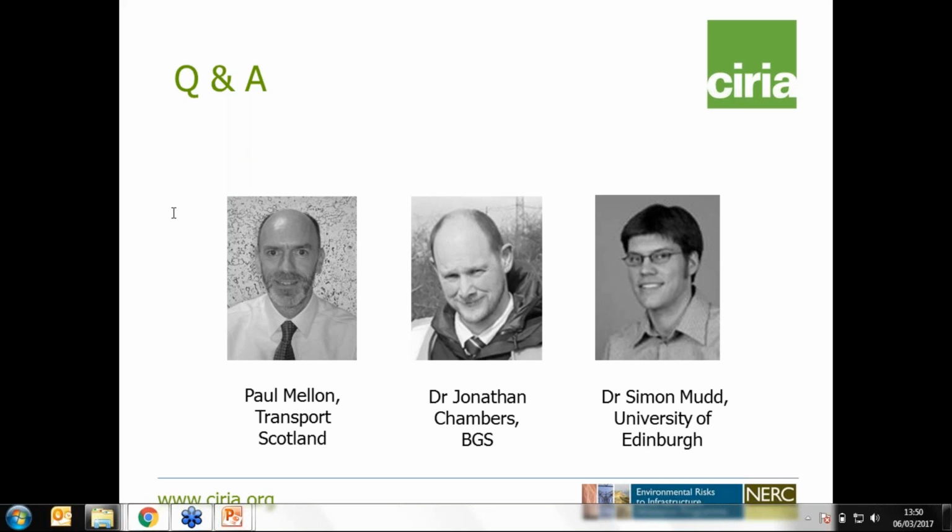So at the moment, in specific sites where we have the data, we are trying to use some of the superficial geology layers from BGS. So that does play a role. Again, it's quite difficult to integrate because the soil thickness is quite heterogeneous. Basically, it leads to a lot of uncertainties in how those groundwater models propagate through our slope stability analysis. So we try to take a probabilistic approach instead of knowing exactly how thick the soil is. But we can integrate those other data layers.